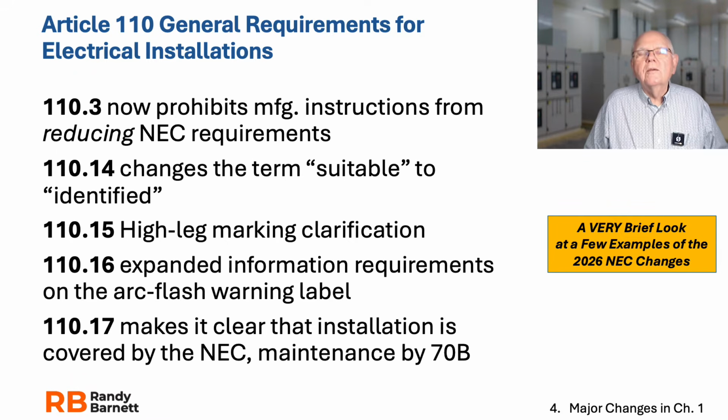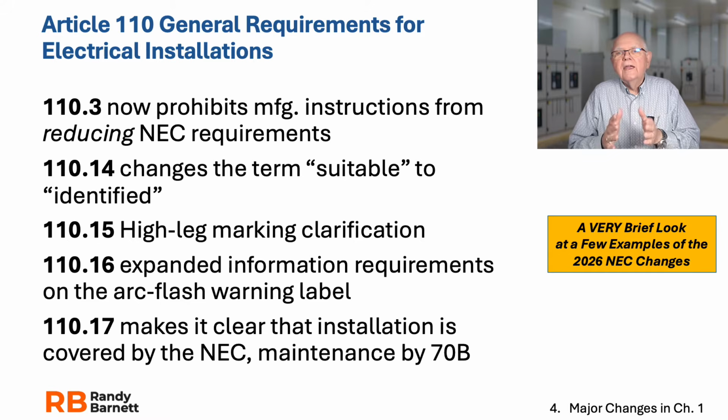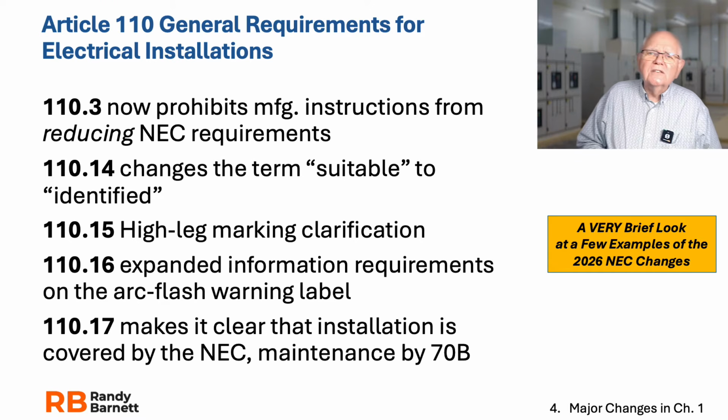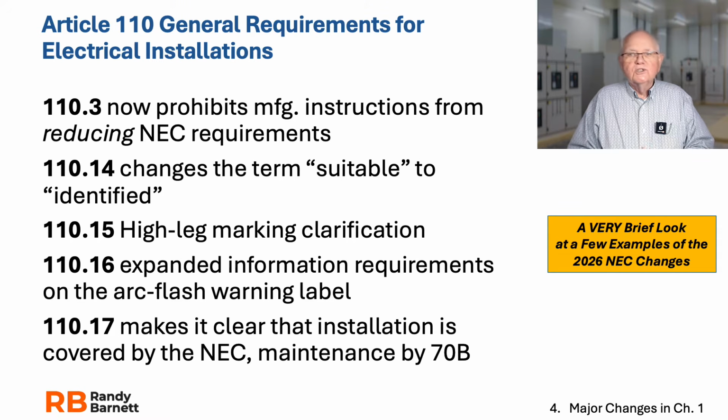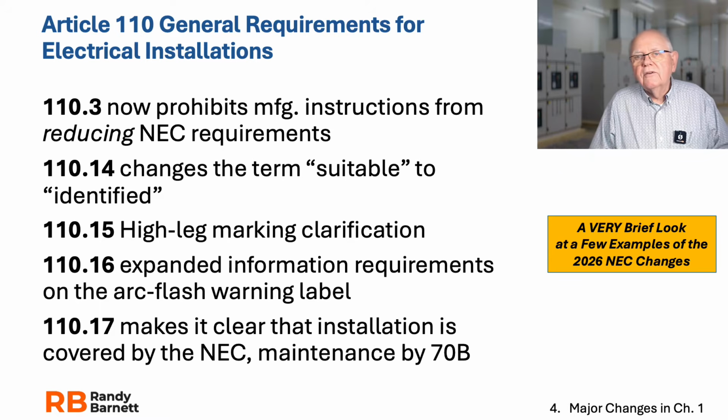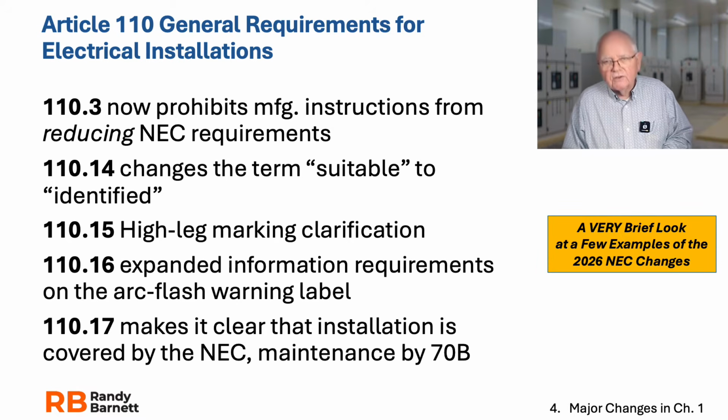But the actual maintenance requirements are covered by the NFPA 70B standard, which was revised not long ago, and it moved from a recommended practice to a standard, which means it went from, hey, it's a good idea, we recommend you do this electrical maintenance on your equipment, to now it's a standard, meaning it's an ANSI approved standard. It'll stand up in a court of law. Hey, this is the maintenance you must do on your electrical equipment. And if you don't do it, there's no maintenance police that are going to come looking after you, right? But if something fails, somebody gets hurt, you have a fire or whatever, there's going to be questions about enforcement of NFPA 70B, certainly.